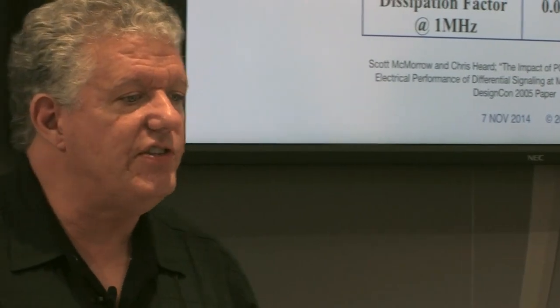But what happens is that in a printed circuit board, we have a combination of glass and epoxies. In order to achieve a lower E sub R printed circuit board material property, we have to mix a high dielectric constant glass with a much lower dielectric constant epoxy to generate an average mixture that we're going to be using. That then poses some issues for the electronic properties.